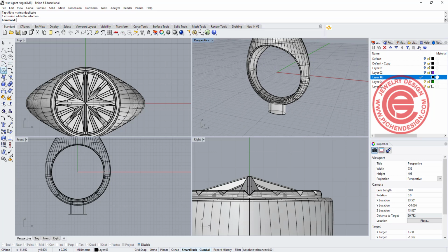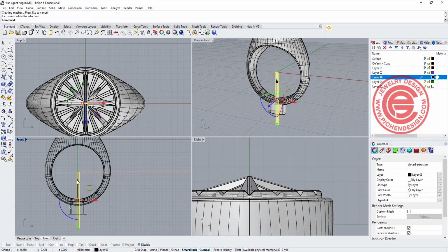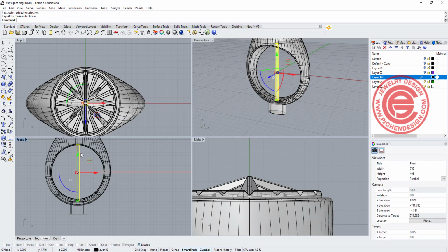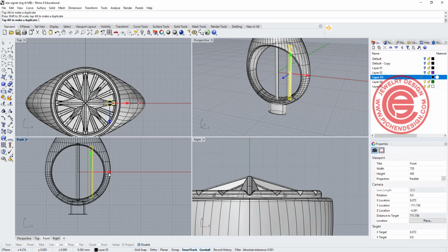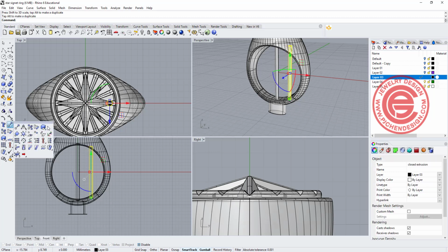But if it is just a solid piece, I might want to put one, and it's about 1 millimeter in diameter, so 0.25, and I want to make another cylinder, and it goes something like this. And this helps the support hold on a little bit better. And maybe I want to make a copy over here, going down a little bit, and mirror that to the other side.